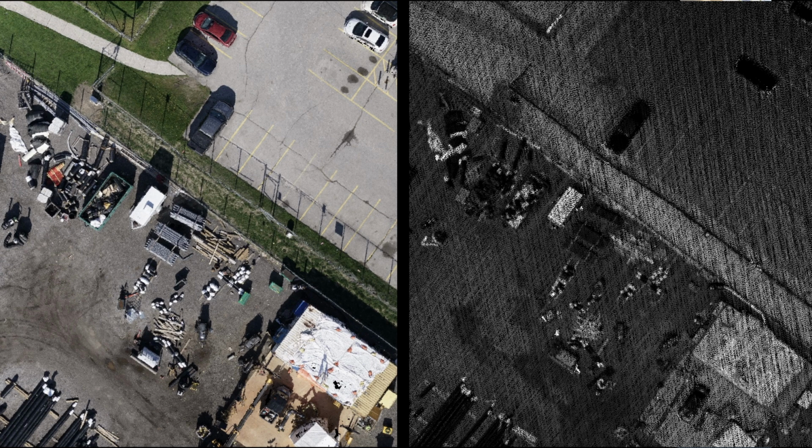With LiDAR, we don't have RGB, but we have intensity. So that essentially is a measure of how powerful the laser pulse was when it came back and was detected. So, the basic principle of LiDAR is that there is a laser emission and then a detection of that laser after it bounces off an object. So if that object is reflective, then the return pulse will have quite a lot of power, and that is how we get to this grayscale image that basically shows us what RGB shows us, but in one color palette at a time.